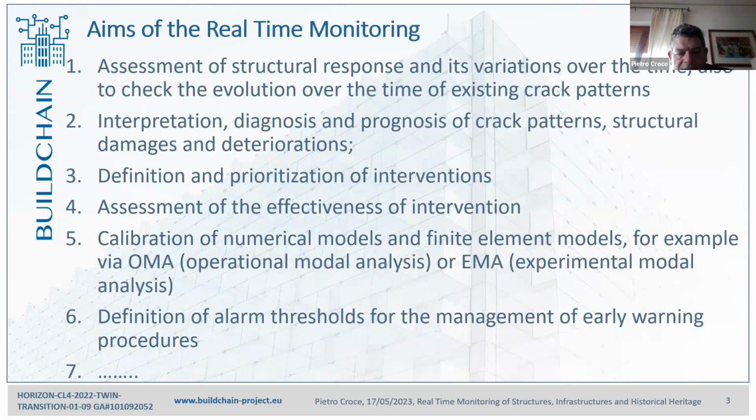What are the aims of real-time monitoring? Some of the objectives have been illustrated by our colleagues in the previous presentation. We have the assessment of the structural response and its variation over time, especially the study of the evolution over time of existing crack patterns, interpretation, the diagnosis and prognosis of crack patterns, structural damage and deterioration.